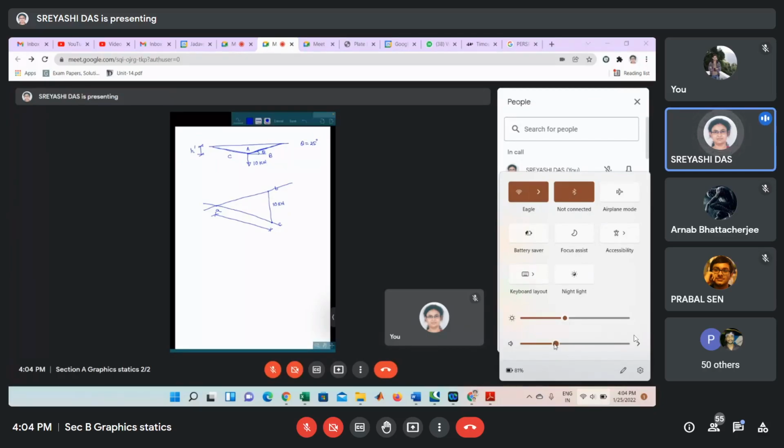Suppose in this form diagram, the name of the force in this member, the name of this force is AB, isn't it? It will be AB or BA, because we have adopted Bow's notation, which takes the convention of the clockwise direction.